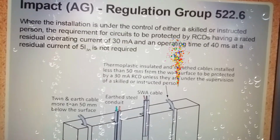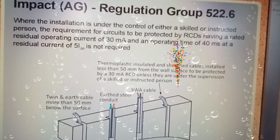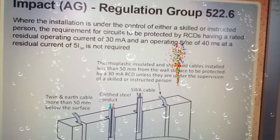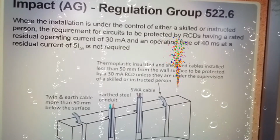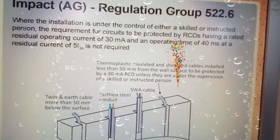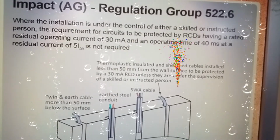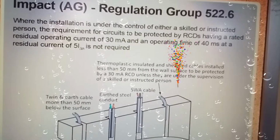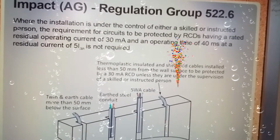Now, impact AG regulations. Here we're looking at the impact on cables, and here you can see twin and earth cable more than 50 millimeters below the surface. Now where the installation is under the control of either a skilled or instructed person, the requirements for circuits to be protected by RCDs having a rated residual operating current of 30 milliamps and an operating time of 40 milliseconds at a residual current of 5 I delta N is not required. Well, I call it 5 I delta N. Thermoplastic insulated and sheathed cables installed less than 50 millimeters from the wall surface to be protected by a 30 milliamp RCD, unless they are under the supervision of a skilled or instructed person.